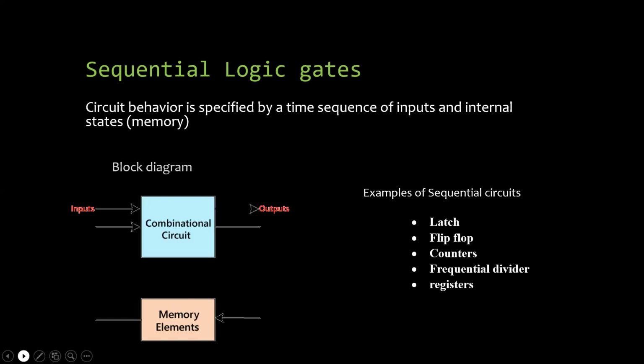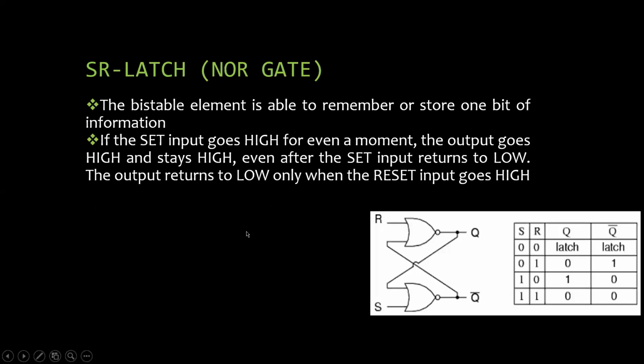Now let's move to our next slide. Here I'm going to design an SR latch using Logisim software. Before that, I would like to tell you that an SR latch can be designed using two gates, NOR and NAND. Here, using only NOR gates, I'm going to design my practical part. Also, the latch element is able to remember or store one bit of information, the last one bit.